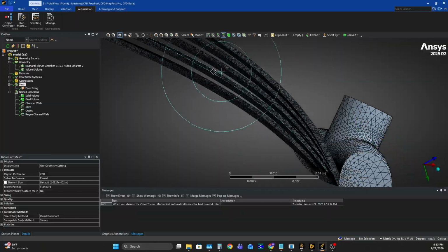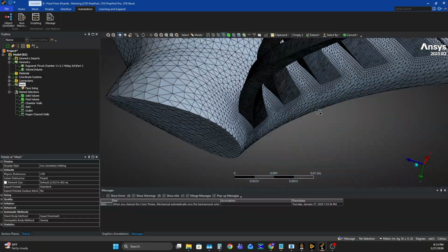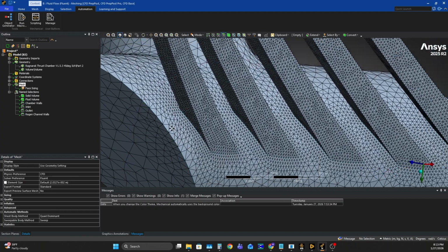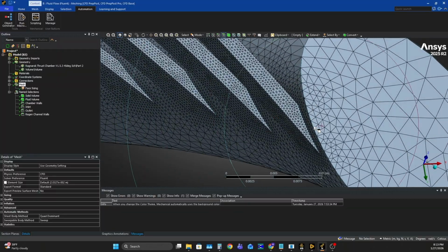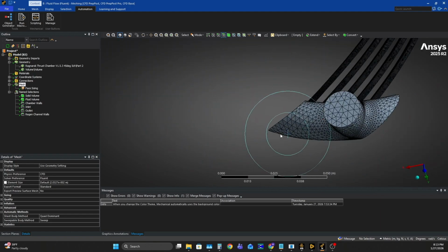And then the other place that we want to look is where the mesh intersects with the annulus. We can see that the mesh is fine, it still is quite fine near the end of the regen channel and slowly becomes more coarse as we move away. That is perfectly fine. We just want to make sure that we still do have a refined mesh towards the inlet on the annulus. And all that looks pretty good.